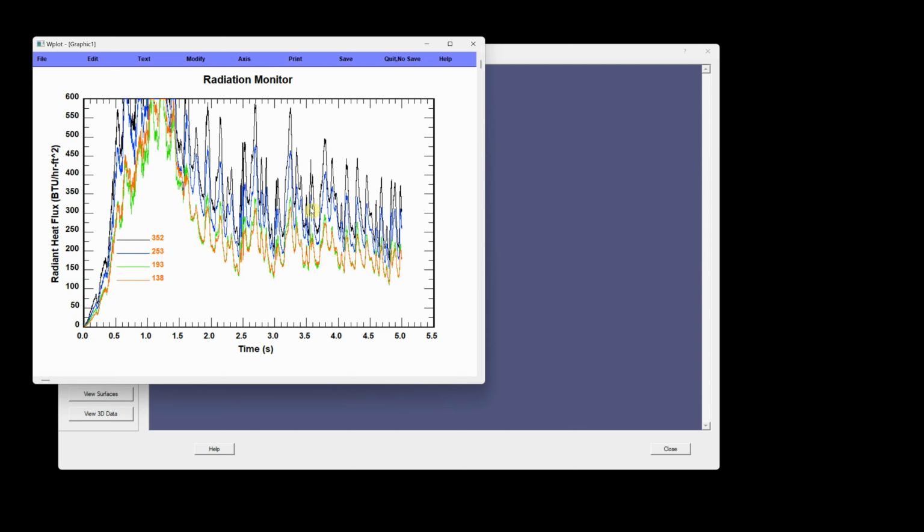One thing you might note is the variation in the radiation flux. It's actually quite large. Looks like about 30%. And this is due to the puffing of the hydrogen flare. So that pretty much finishes this presentation that I wanted to show: 3 different ways of predicting a hydrogen flare and comparing it to experimental data, which shows that the code is predicting answers right in line with what you would expect compared to measurements. And so that concludes this tutorial.